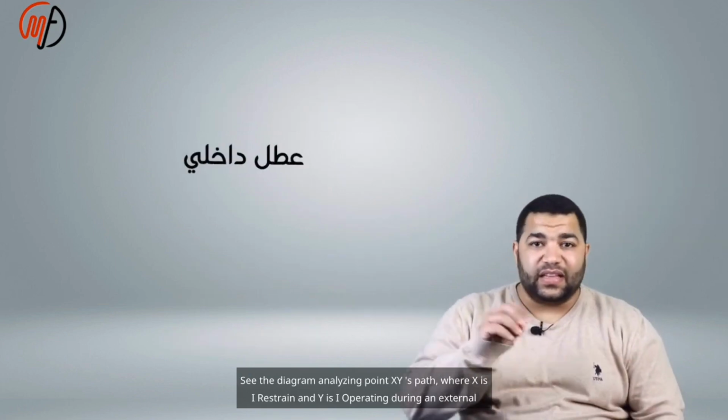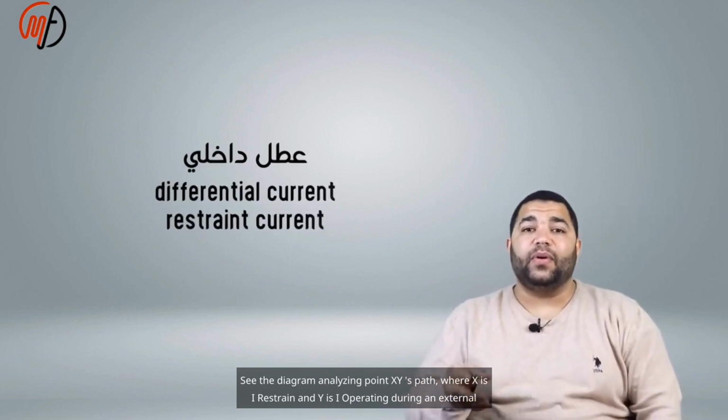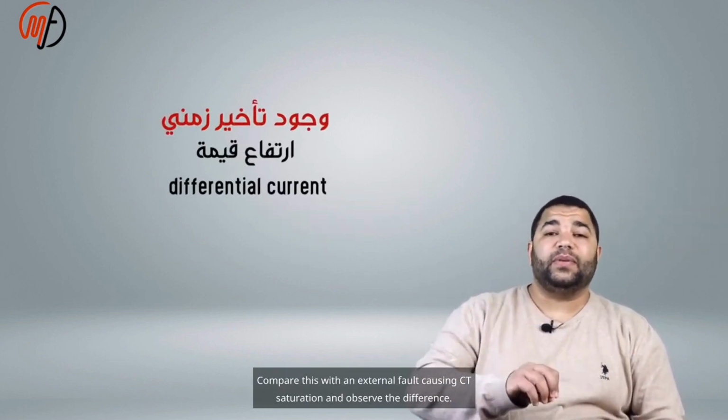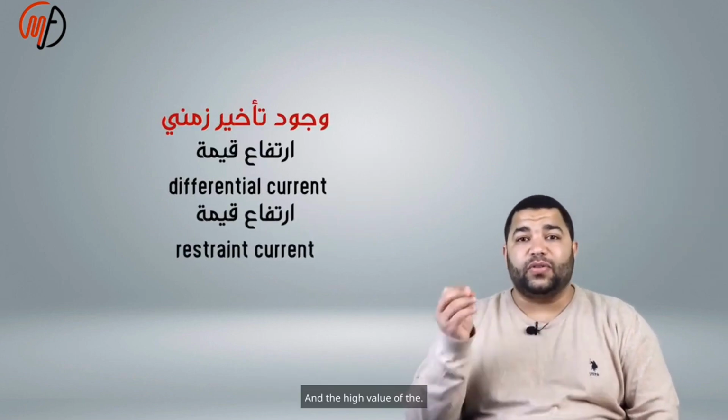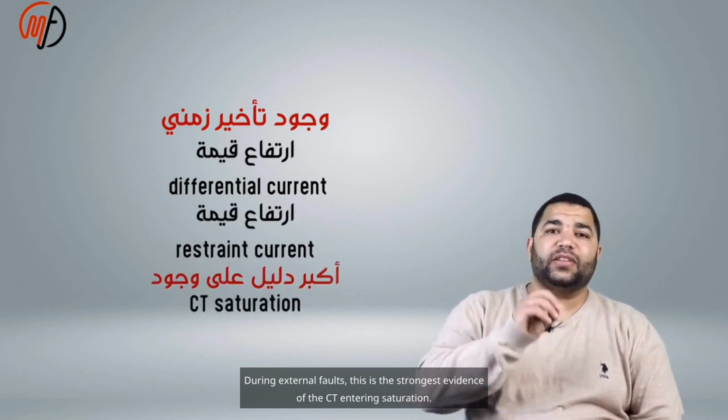See the diagram analyzing point XY's path, where X is I restrain and Y is I operating during an external fault without CT saturation. Compare this with an external fault causing CT saturation and observe the difference. The high value of the differential current during external faults is the strongest evidence of the CT entering saturation.